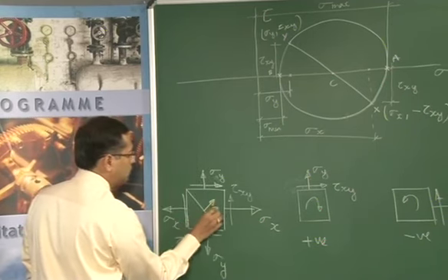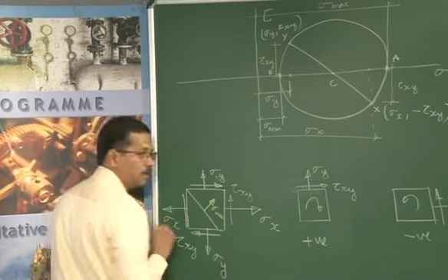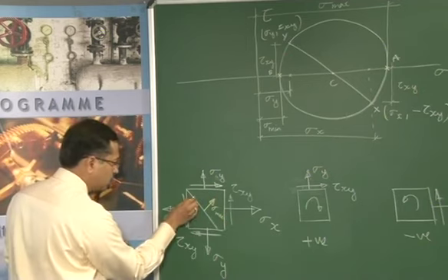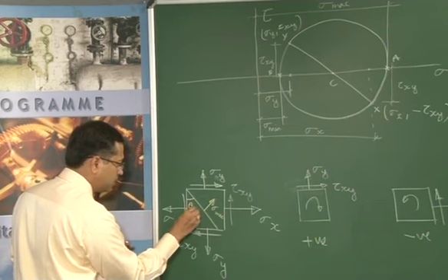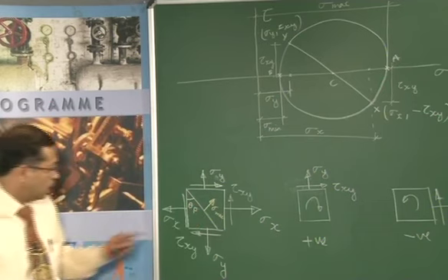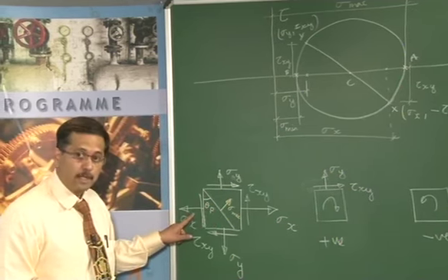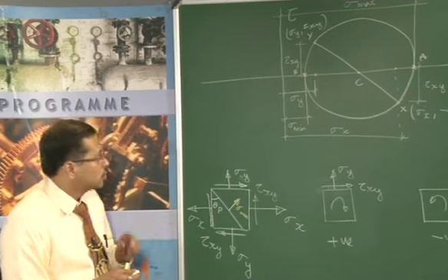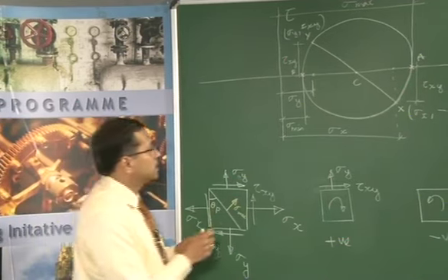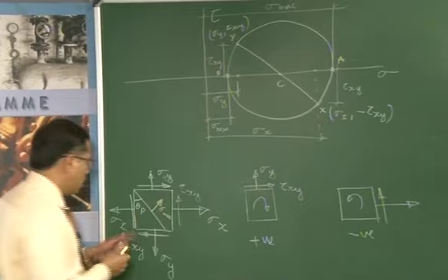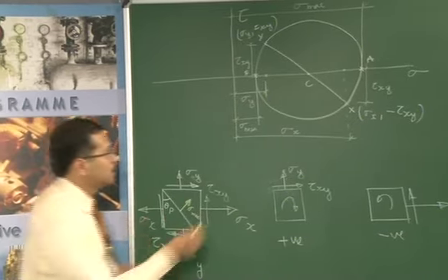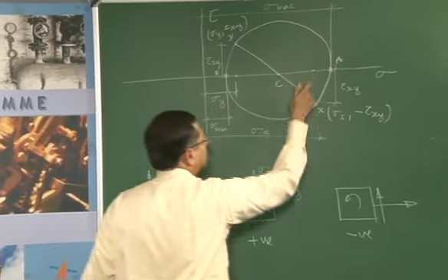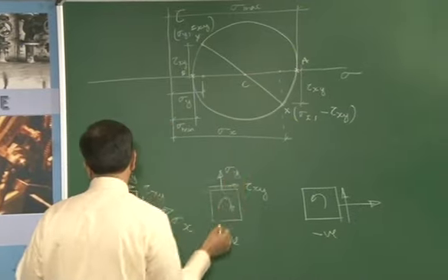So, this is sigma max, the normal stress on this plane, and this corresponds to theta p, which is the principal plane. Now, this one is measured with respect to sigma x. The same theta corresponds to when we measure it with respect to the sigma x axis. Sigma x axis is this line corresponds to this value.